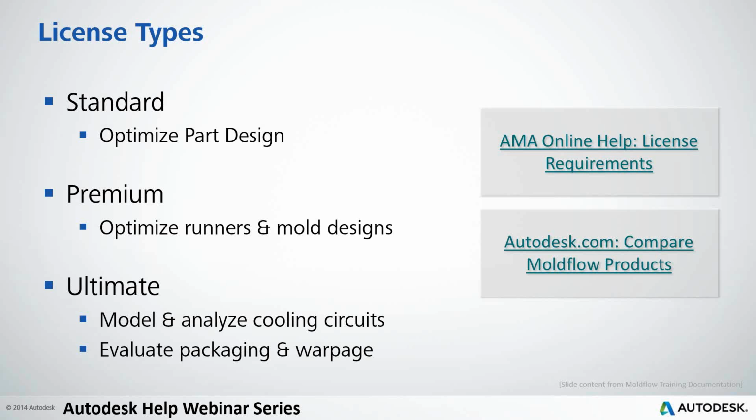So in this case, for standard, all the analyses are based around part optimization. For premium, you're getting a little bit more complex, going into optimizing the runner and mold designs. And then finally, with the ultimate license, you're going to get a few more features, going into mold cooling circuits analysis. You'll also be able to use packing and warpage analysis as well.